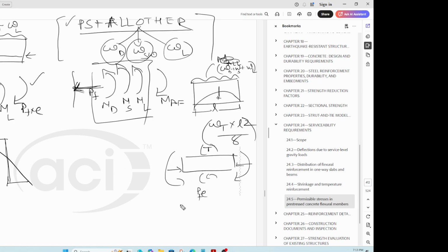Why is this final? This is final because the stress in the bar is relaxed. It is not the same value that you and your friend pulled the reinforcement member to, right? You stretch the reinforcement to cause tension. So after that fact, it has relaxed a little bit, and you have slightly lesser stress. So your PF value, we are talking about the moment, which is PF acting at an eccentricity. So that is causing a tension on the top, compression on the bottom. Compression is like that, tension is like that. You find out the moment caused by that PE moment, which is P final times E.